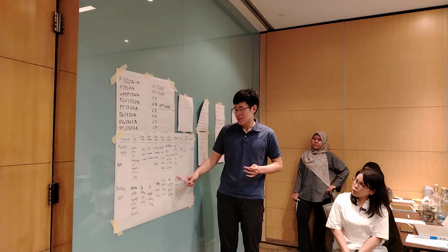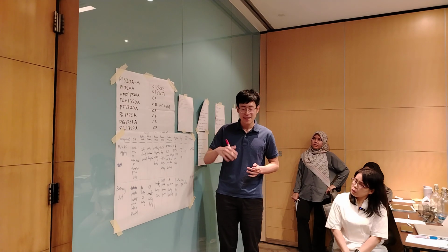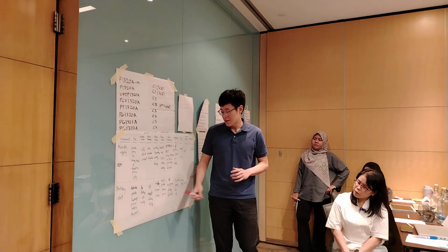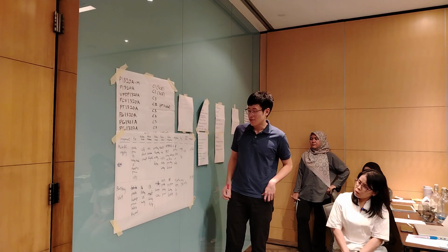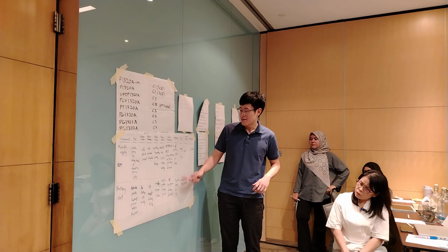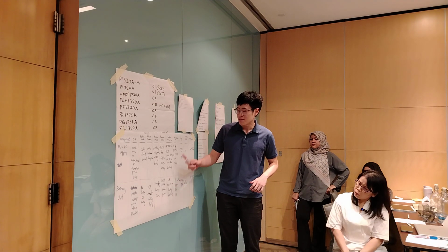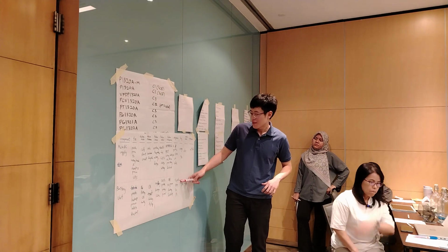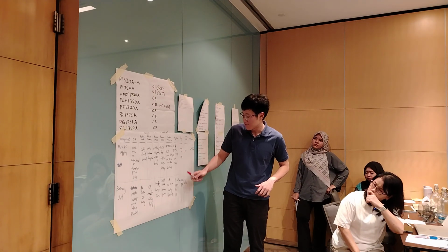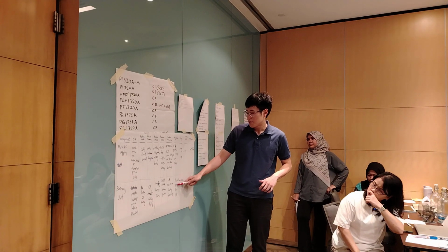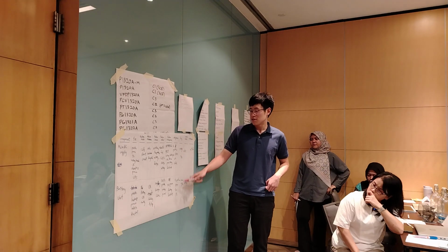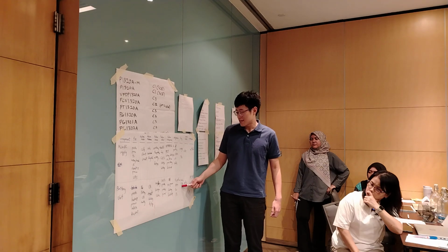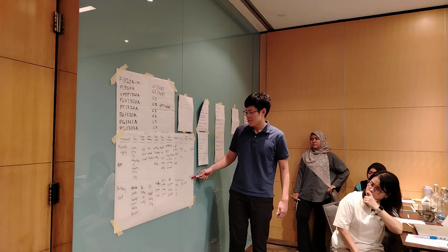And in a very serious case, because the operation cannot monitor, maybe some equipment is having high pressure and they cannot access the panel, and it might cause an explosion or anything. But the less serious one is just no power during blackout. For mitigation, we have to perform PPM for the circuit breaker, which is during every TA, because we can only switch the circuit breaker on and off during the TA, with work center electrical and TBA.